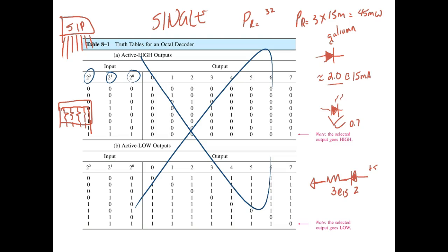You understand this? And then you're going to have DIPs. For 7-segment displays, since we've got to have one resistor per side and there's no common, what we'd use here is a DIP. But these are called resistor packs, and you'll run into a lot of these in digital because we're always pulling stuff up. Pull-up resistors and pull-down resistors are usually SIPs, and then resistors are usually going to be DIPs, because we're not dealing with a lot of current in digital. We're dealing with ones and zeros.